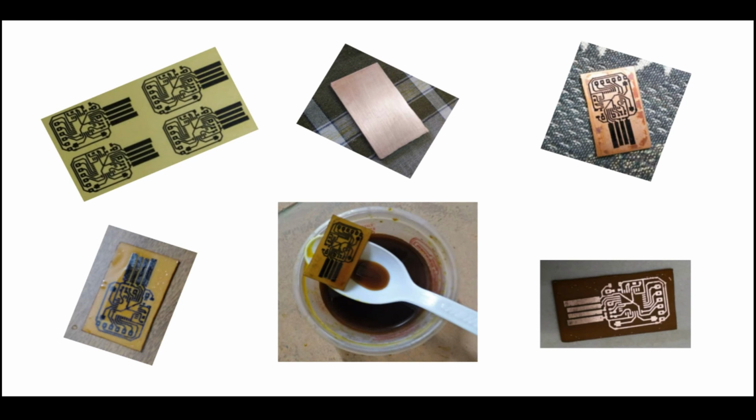to have ferric chloride. This is again available on eBay.in, for 100 rupees. You dip the PCB into it for 10 minutes. It will be available as a powder. Mix some water, dip this, and it should automatically take away all the copper around the circuit which the ink doesn't protect. And you clean it, and you'll get the final product like this.